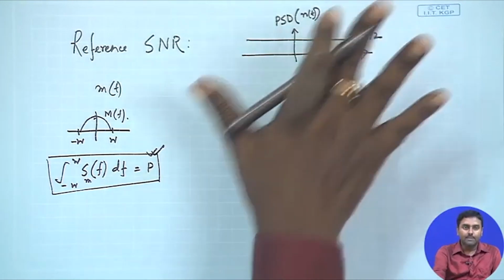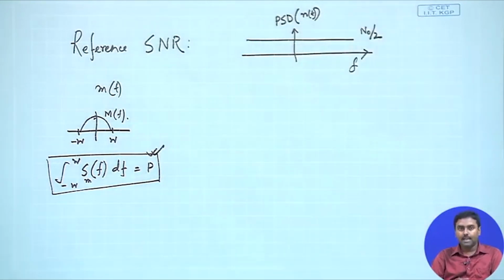This is something we know already, the noise characteristics, and we also know that the noise follows Gaussian statistics. That means, at a particular time you sample from the entire ensemble of noise signals that are possible, and then if you plot the histogram with normalization, you will get a Gaussian PDF. And this noise will be added to the signal in the channel, which is why we have called it additive white Gaussian noise.